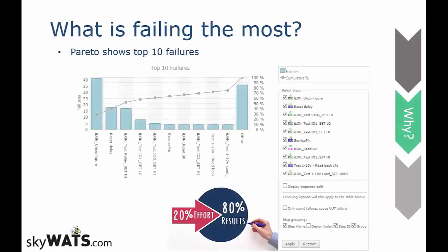One level deeper we would typically look at the most frequent failures. This doesn't have to be on one specific product. It can also be the most frequent failures at a product family or factory for that matter. Applying the Pareto principle to these, you'll start to get the ability to weigh effort versus impact and get improvement initiatives with higher returns than before.